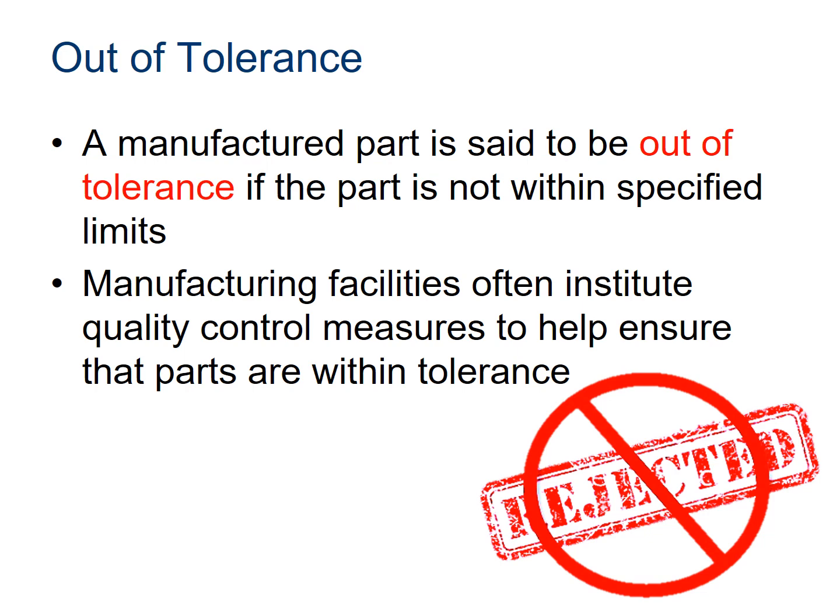Actually, every manufacturing facility I've ever been in has a way of separating and segregating the non-conforming parts from the conforming parts. When I was working at Charbroil, whenever we had a non-conforming part made, we had to make a non-conforming quality report, also known as an NCQR. We had to track down why that particular part was not conforming to quality standards.